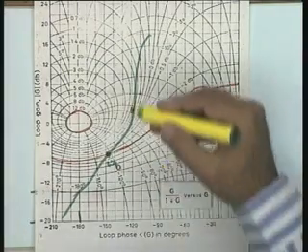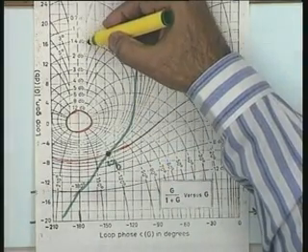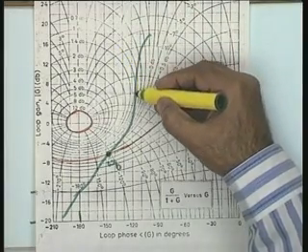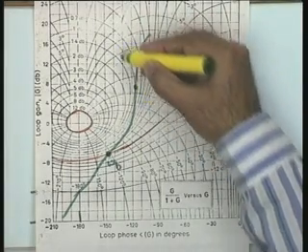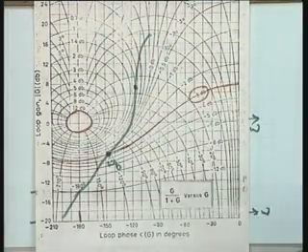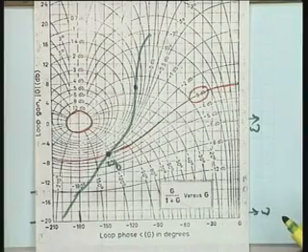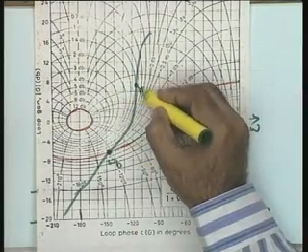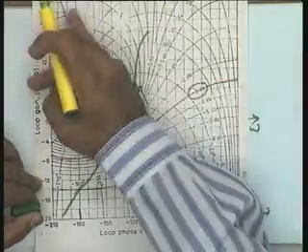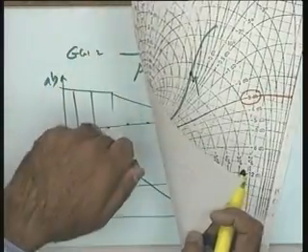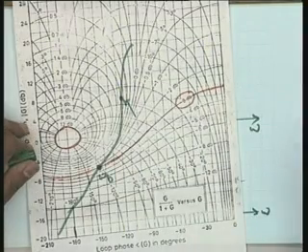That is why the Nyquist chart is an important graphical instrument in our hand as far as the frequency domain design is concerned, because reading of the bandwidth is easy. Now think of omega r, or MR, in this particular case. Please see that in this case, the plot is tangential to this particular circle, and I can get the corresponding value of MR. And if I have to read the value of omega r, naturally I will take the magnitude and phase angle and read these values on the Bode plot. The magnitude and phase angle will be available to me.